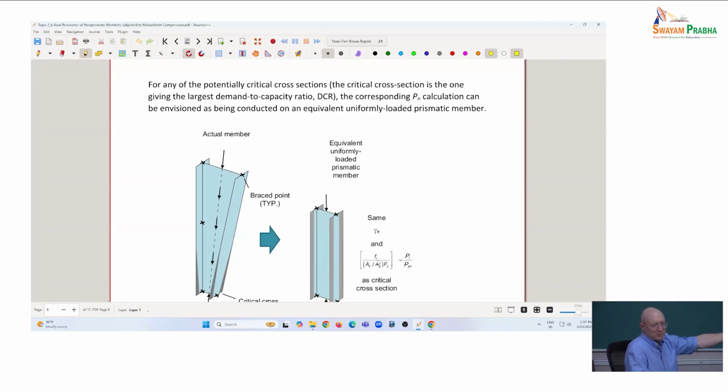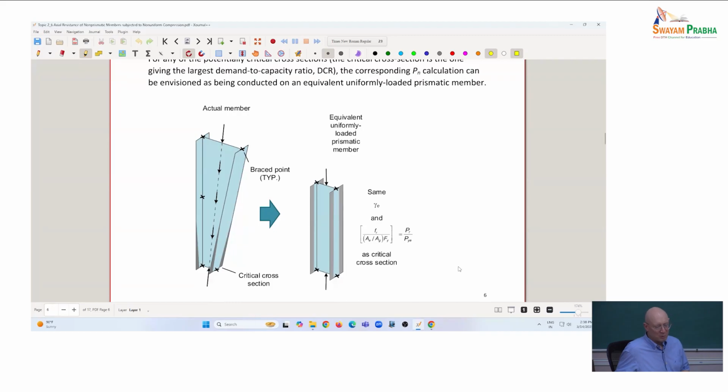have a cross-section strength that would be impacted by local buckling calculations. So you've got cross-section strength, now you hit that with a chi factor to get your overall member resistance. In that case, absolutely, all you need to do is identify, well, what's the critical cross-section? That's the one I want to do my calculation for to get a member strength. And then the chi factor pulls in all the attributes of the overall buckling of the member. So once we've identified that critical cross-section,